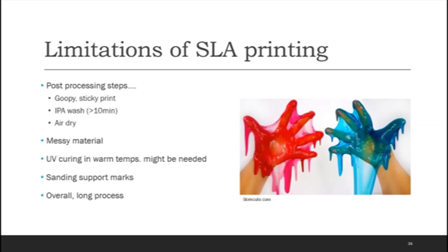And then there's sanding support marks. After you cut your supports, you still get a little bit of residue in your print. Some people don't mind if the support marks are in a place that you definitely don't care about, in the base, let's say, then that's completely fine and you can ignore it.